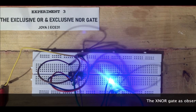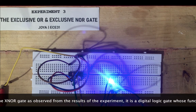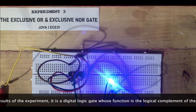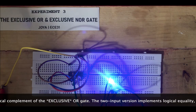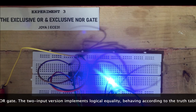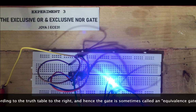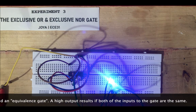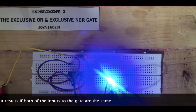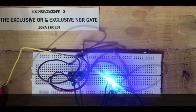The XNOR gate, as observed from the results of the experiment, is a digital logic gate whose function is the logical complement of the exclusive OR gate. The two-input version implements logical equality, behaving according to the truth table to the right, and hence the gate is sometimes called the equivalence gate. A high output results if both of the inputs to the gate are the same.